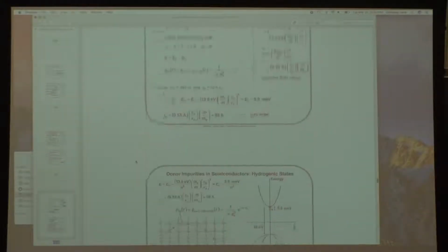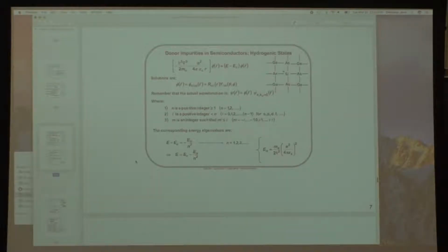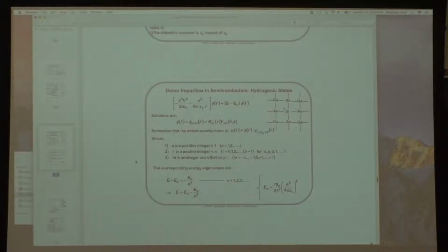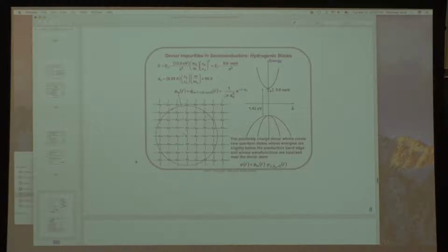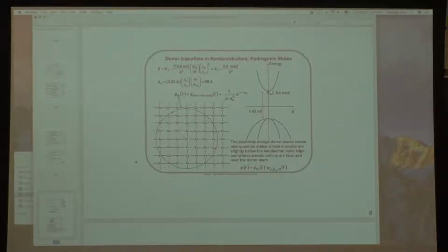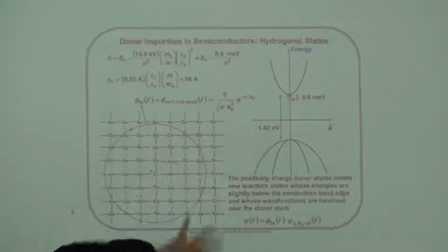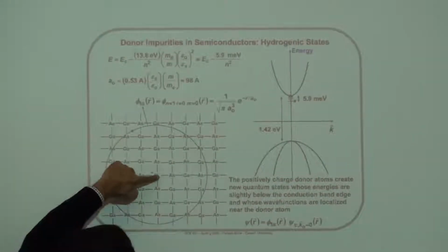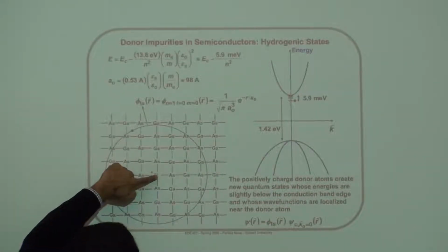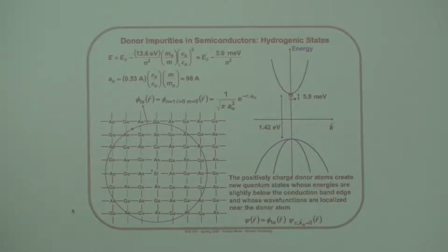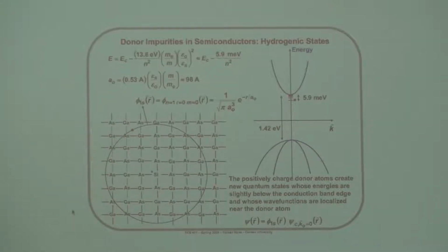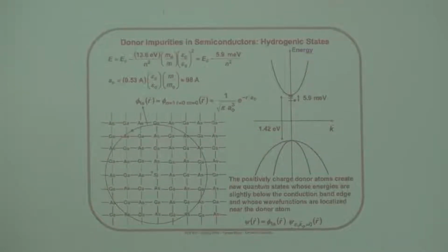All right, I'll come to the exact quantum picture of this later, but essentially this is what we're talking about. I talked about silicon, but if you had a gallium arsenide crystal, and this is gallium, and you replace it with silicon, silicon is to the right of gallium, so that's also an N-type donor. And here are the states that I was mentioning.